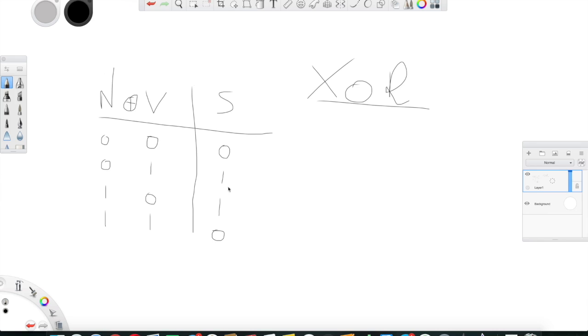Therefore, the sign bit is 1. N means the actual output sign is 0, it's positive. However, the overflow flag is 1, indicating that an overflow occurred and this sign is wrong. Which sign? The N bit. Therefore, I complement the N bit and it will be 1. So the expected sign of the result is 1.